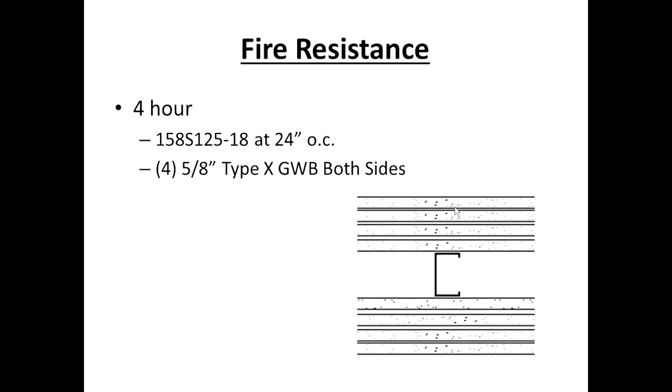At that point, all the exposed board is gone. The fire has pretty much consumed it. It's calcined, or it's disappeared. But the stud has stayed in place. The stud has kept its ability to hold screws and therefore gypsum panels on the opposite side. And I can't underscore that enough. That is critical, because if you lose your holding power of being able to hold the fastener and keep that panel in place and in plane, you lose your fire test. Steel plays a key role in fire resistance.